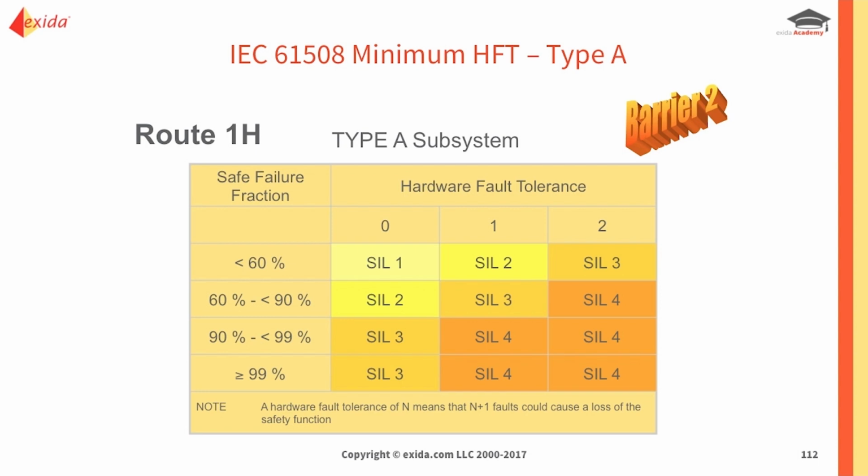What about B? Well, this is an exida definition, not the standard definition. Everything else, like a microprocessor. Why is a microprocessor in type B? By the time you ever have a chance of collecting enough failure rate data, it'll be obsolete, off the market, and replaced with a new one. So it's a type B. So just remember those definitions.